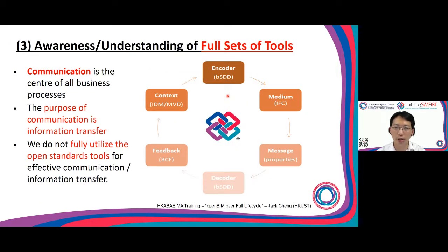Number 3 is we should consider the full set of the tools. Note that why we have so many open standards basically is for communication. But for communication, they actually have different purposes. We shouldn't only capture the digital model using IFC, and it's not enough. This one is only one part. But for example, for communication, we still need BCF. For the terminology, we still need bSDD, something like that. For workflow, we still need IDM, MVD. So this is something that we need to think about.